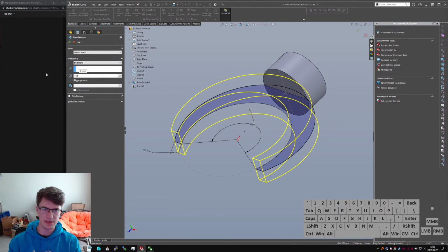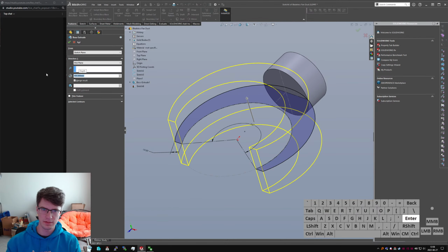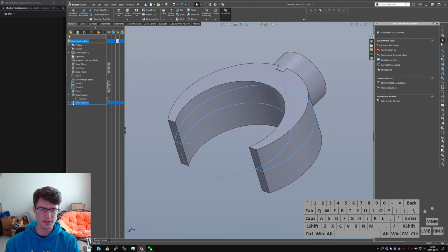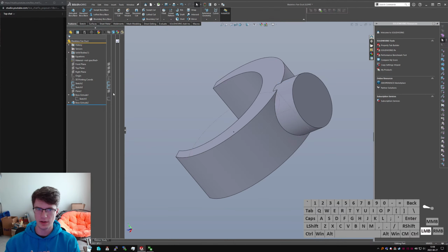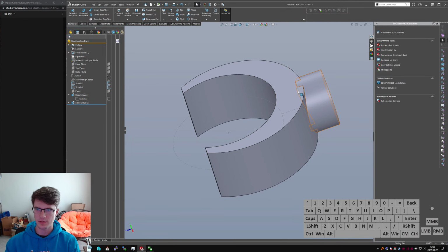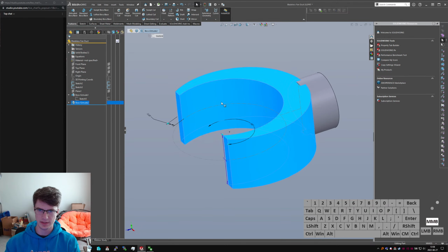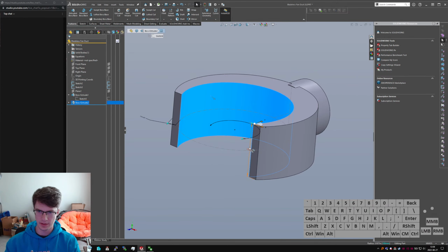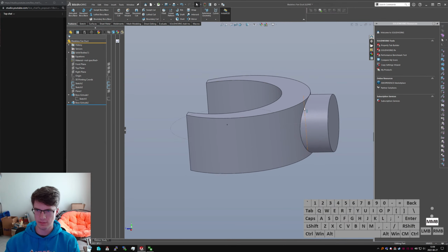Let's just take a guess and say D1 at sketch 5. Nope, doesn't exist. Sketch 4 also doesn't exist. Make it 100 for now. And then do a quick, oh, it was sketch 5. Which dimension is that then? Oh, there is no dimension. That's right, because I defined it up in sketch 3. D1 at sketch 3. So we can select the feature dimension, which is why it's in blue. Make this equal to D1 at sketch 3. There we go. Now we got a nice even matchup.